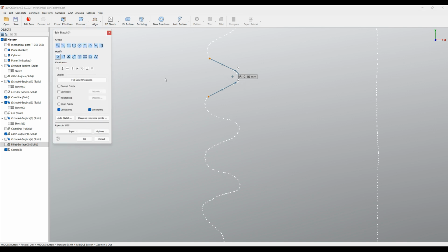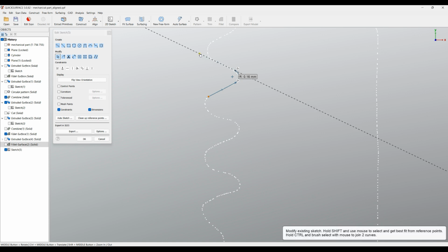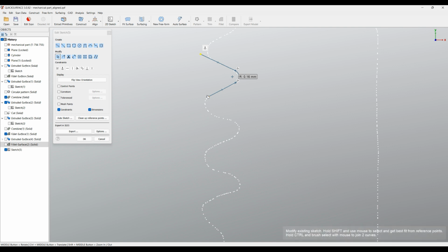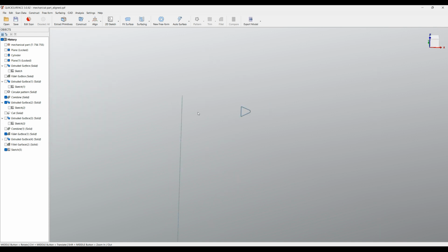Then you press OK. Try to manipulate now and move this a little bit out, so you can get this profile correctly to cut material from the main body. The final step in this sketch I'm going to do is just to close it. Now I have my profile. I need to create the helix.